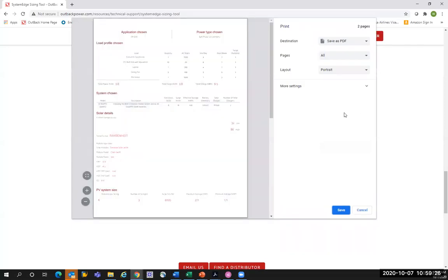I want to say, Mark, I'm really pleased that the order of this tool starts with the load calculation, because that is how sizing these systems, or thinking about storage in general, should start. I know a lot of people often think, let's think about the PV first. But in a battery-based circumstance, we really do want to start with the loads. Then we look at our inverter and battery option based on those loads, and then pair the PV last. So I just want to applaud the sequence of this, because it's really how you should be thinking about these systems. Well, thank you. I appreciate that. I put some thought into it.